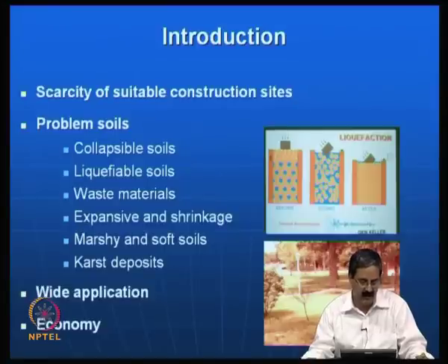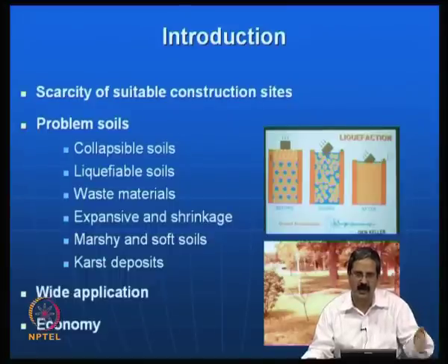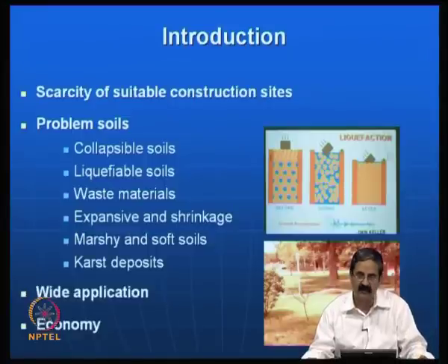Another case is what are called karst deposits. In some natural formations there are soils where holes like sinkholes form. We do not know exactly how they form, but when the soil comes in contact with water, the soil is lost and suddenly you find a cavity. So, this is a very big risk.